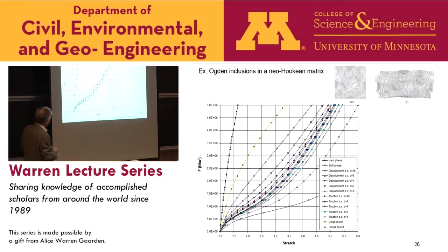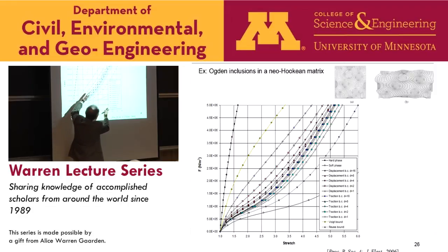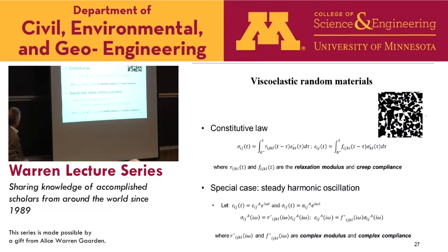So actually this can also be extended to thermoelasticity, even finite thermoelasticity and so on. For this particular situation, we got the result that on the scale of 16 by 16, larger than the grain size, the results from displacement and traction boundary conditions were almost overlapping. So here we go. This is kind of an estimate of RVE size. One can apply it also to viscoelastic materials.